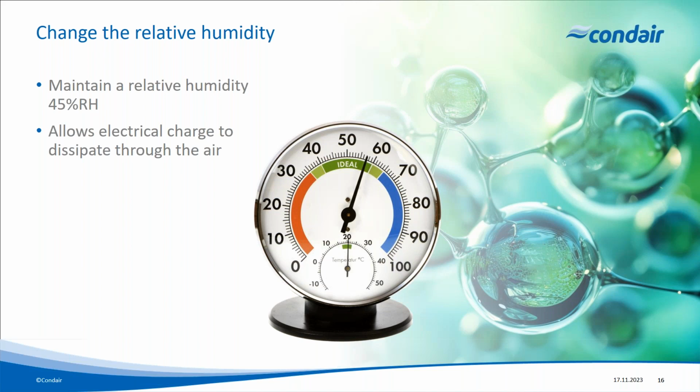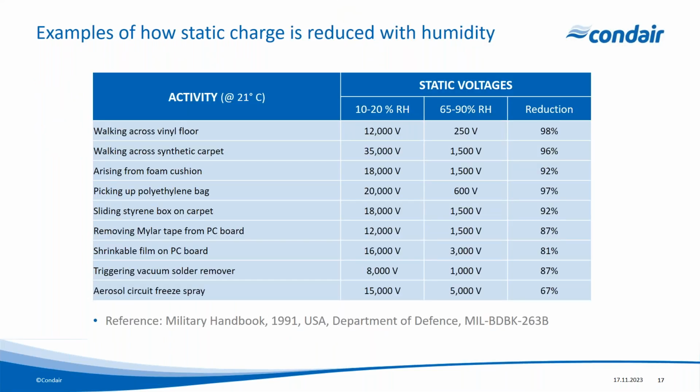So for a lot of applications, it's critical that we humidify. And the data that we can see in this table demonstrates very well the sort of effectiveness that humidifying will deliver. This is based on experiments detailed in the military handbook for the United States Department of Defense, published in 1991. They conducted experiments that detailed the static voltage of various activities at high and low relative humidities.